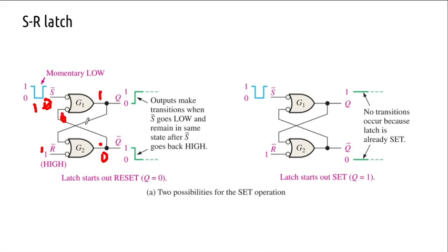That's why even I get confused occasionally. So you would have to provide feedback from the output that goes high. Here Q bar is now 1, and when it is fed back there, it gets cleared. Then it reinforces. Even if you change this, remove this set condition, the bit is retained. The Q is stored. That is memory. The bit that was set is retained there, latched, right?